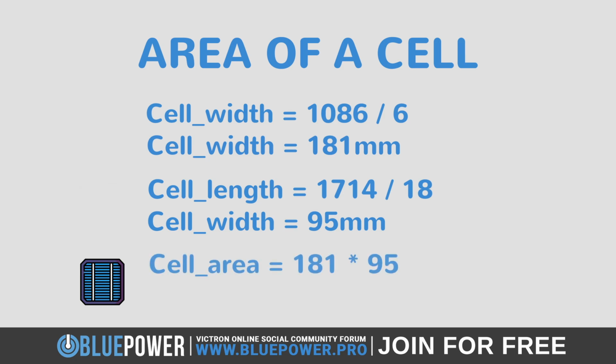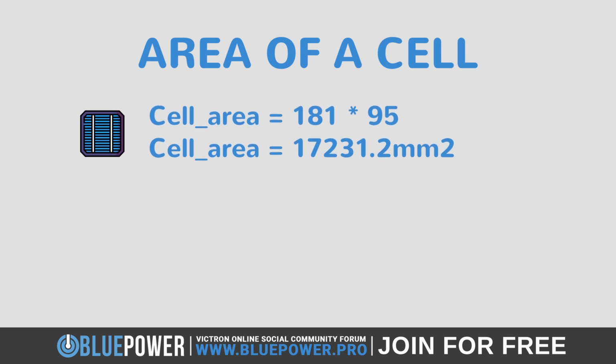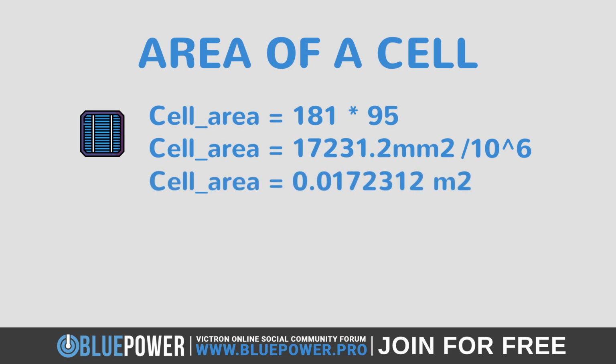Now we need the area of each cell, which we can do by multiplying 181 by 95.2, which works out to 17,231.2 millimeters squared. However, as we need this to be in meters in order to multiply it by the solar irradiance of G in our formula, we again divide this by 10 to the power of 6 in order to convert it to meters.